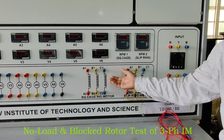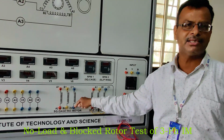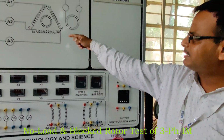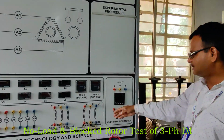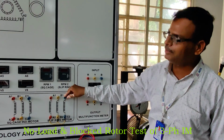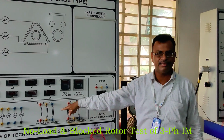See that this one is the squirrel cage induction motor. There are 6 terminals here. 6 terminals means by connecting these terminals you may connect in star or delta fashion. And in this circuit diagram, the connection is in delta fashion. Similarly, this connection is given for the slip ring induction motor. So we have to perform the no load and blocked rotor test on this squirrel cage induction motor.